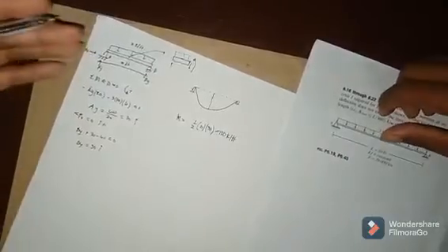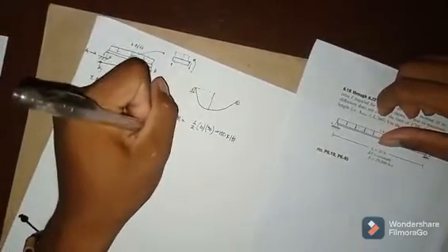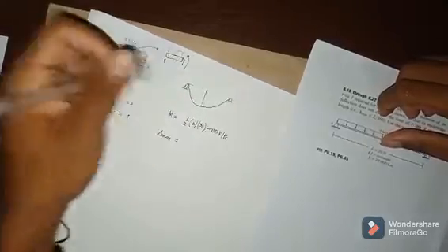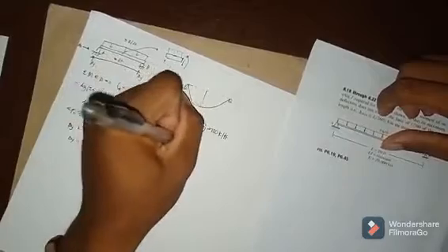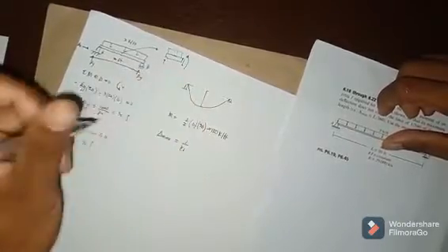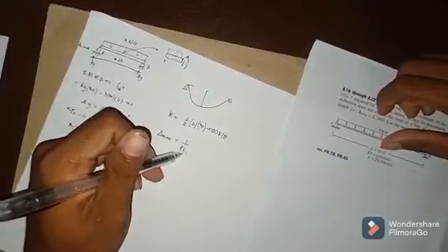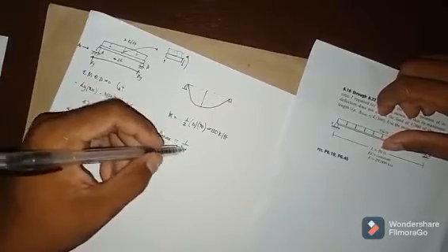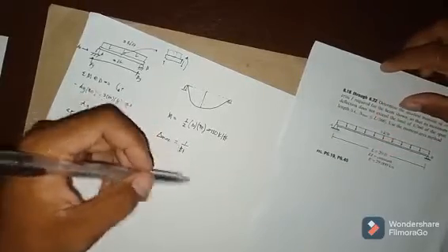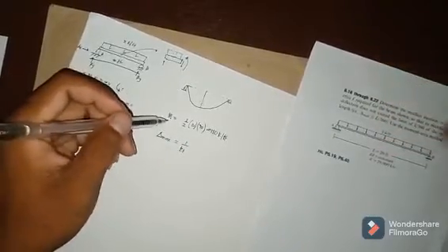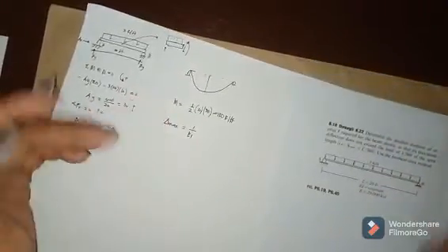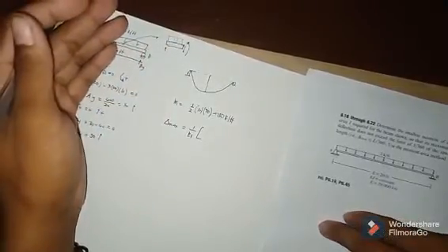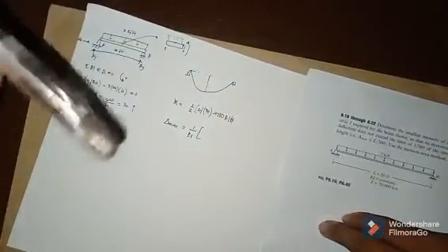So, we all know that in solving the deflection, the formula is for the maximum, so we label it the maximum: 1/EI, and we all know that EI is constant. But we will solve for the inertia later, because that is also what is being asked in our problem. And then times the area of the moment times its centroid.